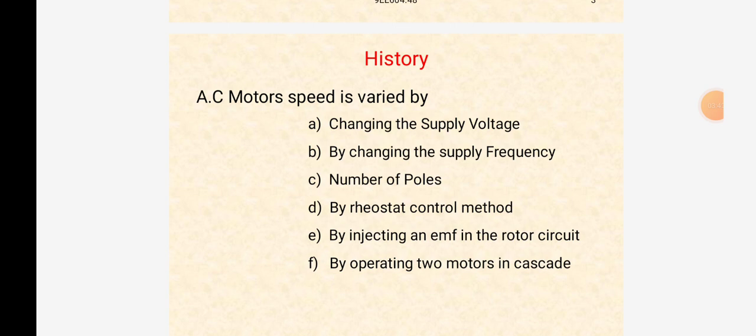Here we have a few advantages of thyristor controlled drives. They have higher accuracy, meaning exact desired speeds can be achieved, greater reliability, higher efficiency of operation owing to absence of moving parts and I square R losses, meaning copper losses, ease of maintenance, low installation cost, lower floor space required, soft start and reduced mechanical stresses, and more energy saving.